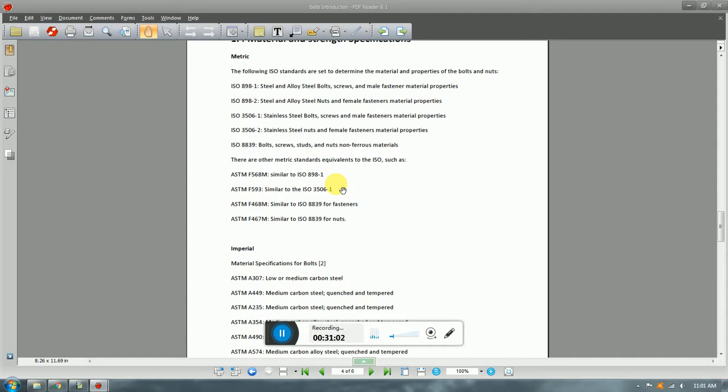The other interesting thing is that in tension, which we will talk about later, typically the first thing that is gonna break is gonna be the threads, okay? So we always use this type of stress area in the threads because it is designed so that the threads break first rather than the head or the shank area, okay? So we're going to always use the threads, and the stress area is going to be in the threads, okay? This is what we're going to talk about.